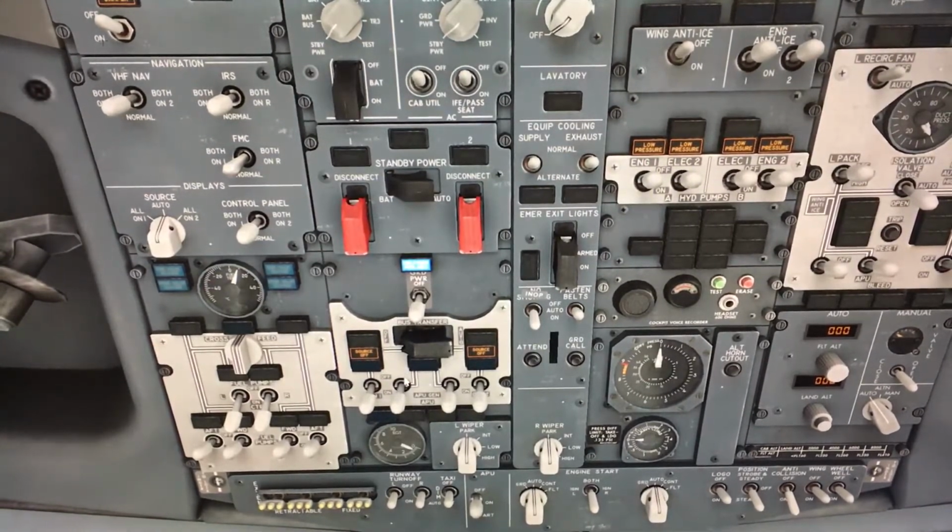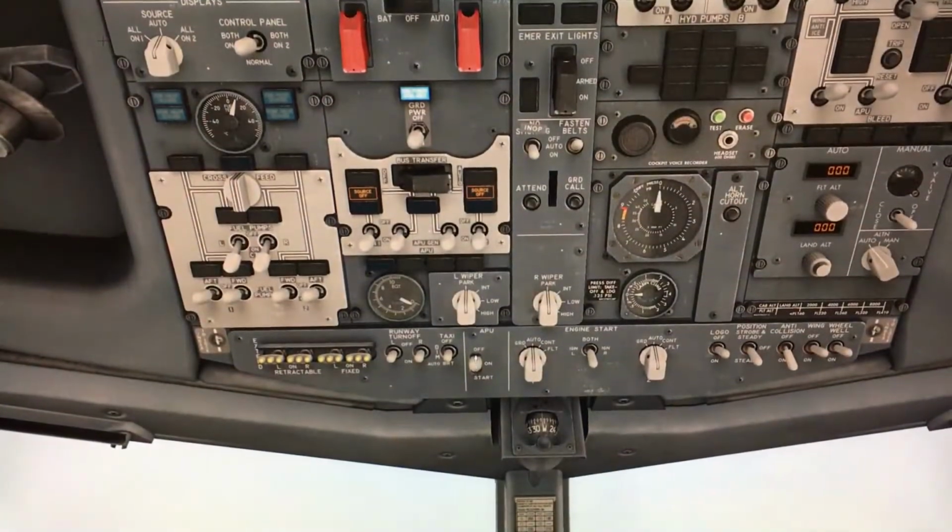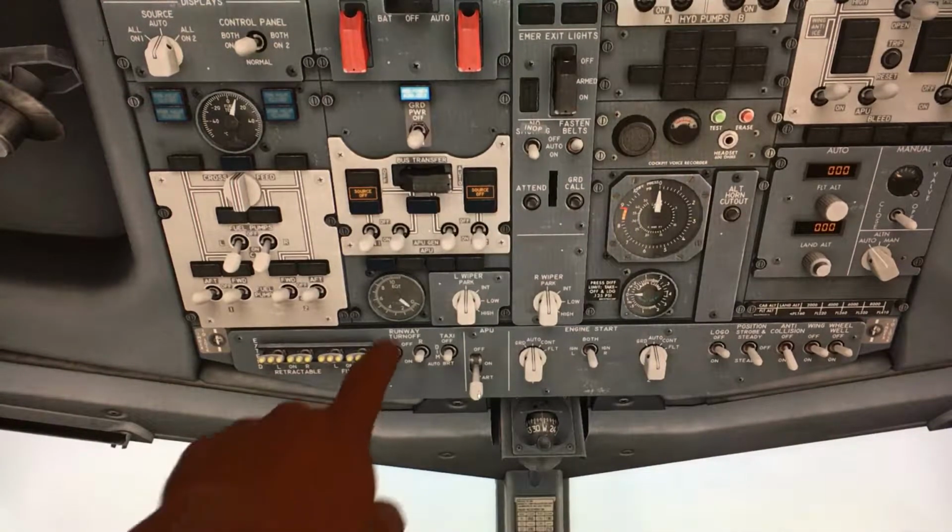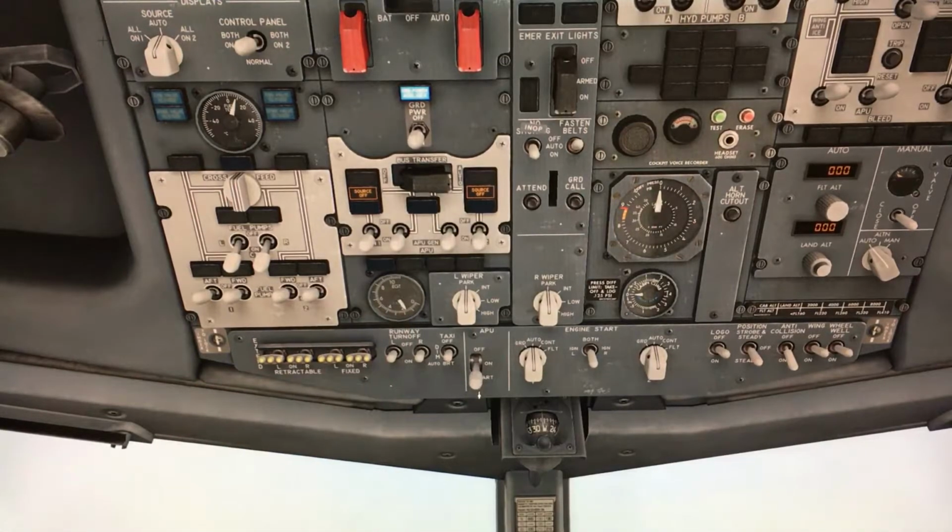We have some fuel feeding to the auxiliary power unit, and next step, we go to the APU start panel. Put this lever down and press it. Before we release it, we have to hold it for 3 or 4 seconds. And after that, you can see this gauge start turning. Now it's a good time to release that lever and let the APU run for a while.